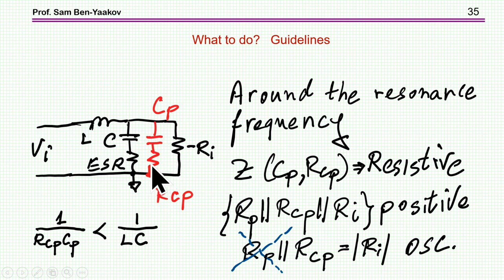At a higher frequency, obviously, I'll have the resistance, which, as we'll see later on, is kind of a problem because it's going to dissipate power. But the crossover point in terms of frequency ranges is that I want this branch to be resistive around the resonant frequency of L and C. Okay, so this is what I want here.